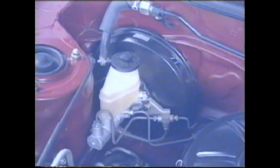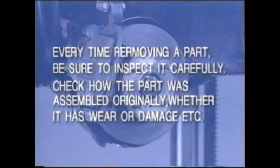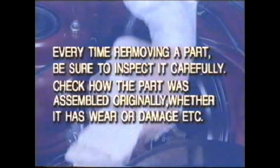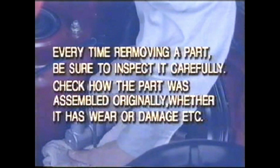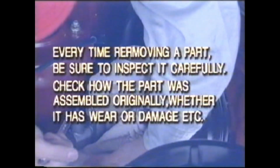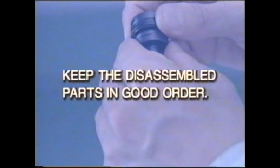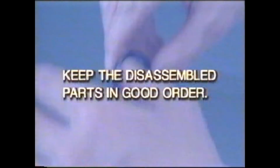The following precautions must be kept firmly in mind when overhauling. When a vehicle is brought in for repair, inspect the vehicle carefully to see whether overhauling is really necessary or not. Every time removing a part, be sure to inspect it carefully. Check how the part was assembled originally, whether it has wear or damage. This is important because some of the causes may be here. Keep the disassembled parts in good order.